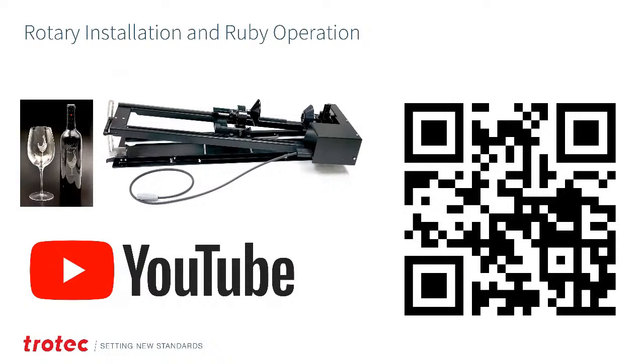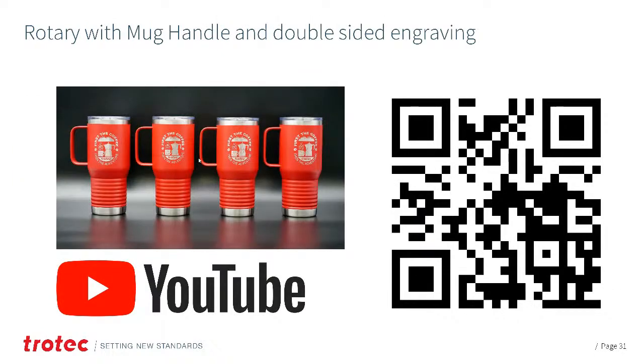If you want to go a step further, I've just recently done one that really showcases the rotary, including running on both sides of a mug handle, compensating for that mug handle, and accounting for the rotation factor. Sometimes Ruby, for example, likes to rotate the rotary halfway through the engraving because it's partway in its rotation factor. This video will showcase how to avoid that. It's also going to show you how to engrave equally on both sides, accounting for a mug handle so that the handle doesn't actually hit the focus head as it's rotating.